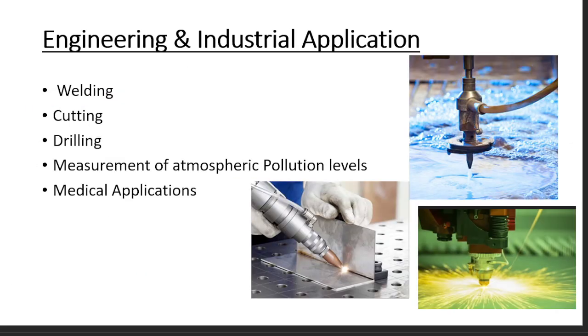The first application of the laser is welding. For welding purposes, we use different lasers, such as an Nd:YAG laser or a CO2 laser. In the welding method, two metal plates are held in contact at their edges, and a high power laser is focused on the line of contact.